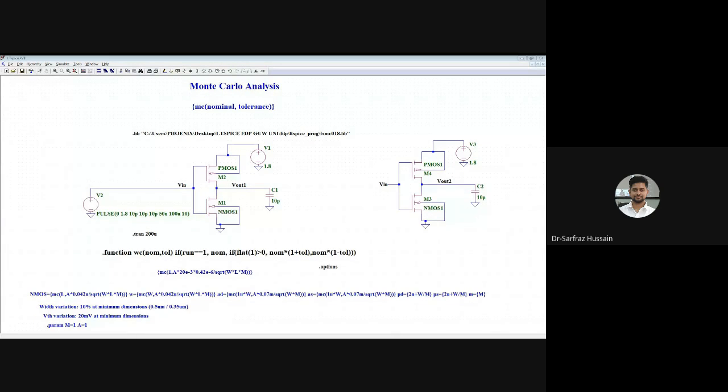Suppose I want to know about the MOSFET model, just click on this one, and here you can get the details of the MOSFET models and all. Whatever models you want to check, you can check over here. What are the models that are available, and what are these model parameters. Suppose an N MOSFET or a P MOSFET is there, and you want to know the description of those parameters, you can look at this particular help topic and check the description.